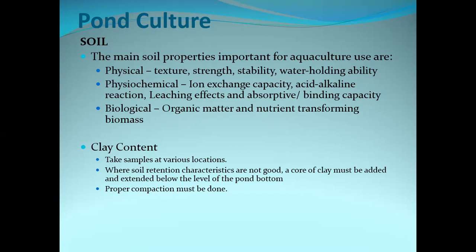So basically, if you have an area that is not very sandy, a kind of intermediate between clay and sandy, so it's suitable enough to do pond culture, it still probably will not retain the kind of water we need to retain to set up ponds. In an instance like that, we could lay the bottom with clay, compact it and roll it within the bottom so that it seals the bottom, and we would be able to utilize it for aquaculture production. Okay?